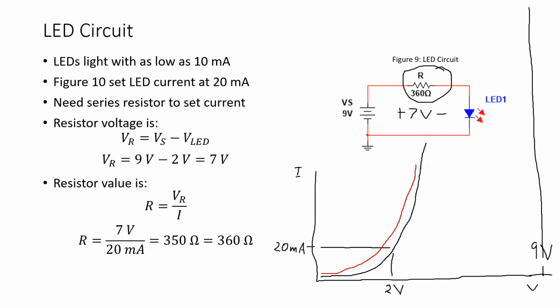We looked at a PN junction diode being reverse biased, where the depletion region becomes very wide and acts like an insulator, and no current flows provided we do not overcome the breakdown voltage of the diode. We looked at an application of a diode to convert alternating current to direct current, which is called a rectifier. And then we looked at placing a capacitor in parallel with the resistor to smooth out the pulsing DC voltage,